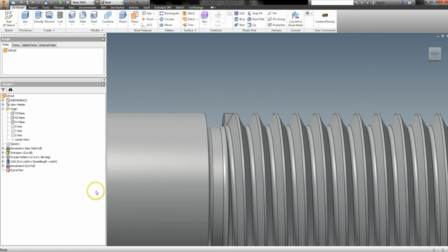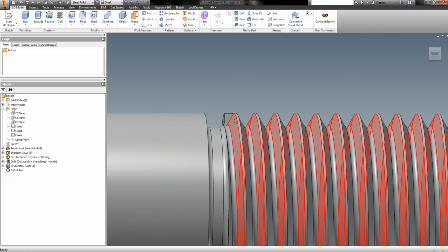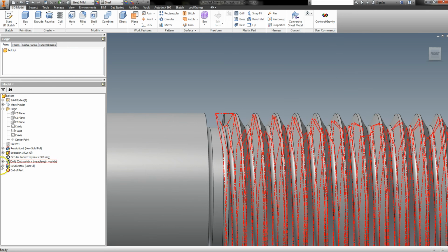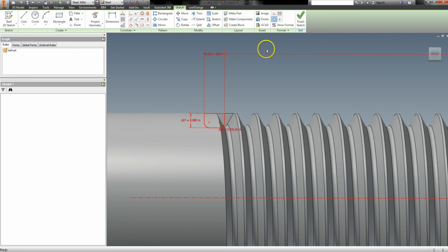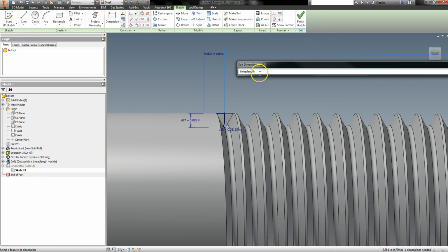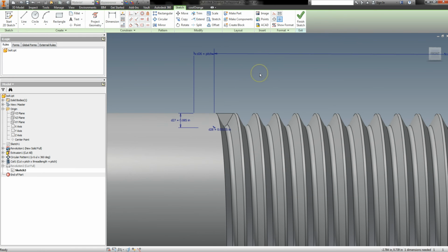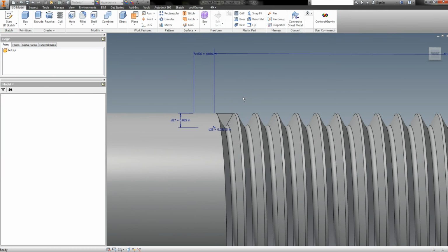So what I probably need to do is kick this relief groove out so that you still get a full thread profile. I need to kick it out 1/2 pitch. So let me do that. We're going to edit this dimension, and I'm going to say plus 0.5 times pitch. So now it sits just beyond the last full profile thread, which should be your working length.